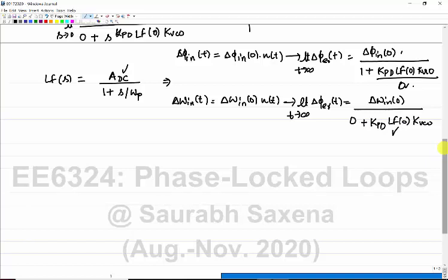There are two things. When you say delta phi n is just because of some random noise, it will change in both directions, agreed. But mostly that noise is not going to take you out of this regime. That noise is pretty small. When we are talking about a phase or frequency step, this is like modulating; you want to change the phase deliberately. Those random noise variations are quite small, and we would never make our phase error equal to 0 for each and every small disturbance that happens.